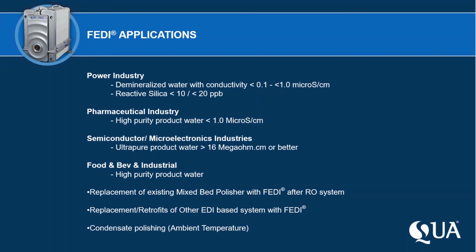So for Fedi or QUAR, we do have EDI projection software to help with the design of your EDI, and I think that's on our website, and you can download it. It would certainly help with putting in your constituents from your RO, and gives you a nice projection on the number of stacks and sizing of power supplies.